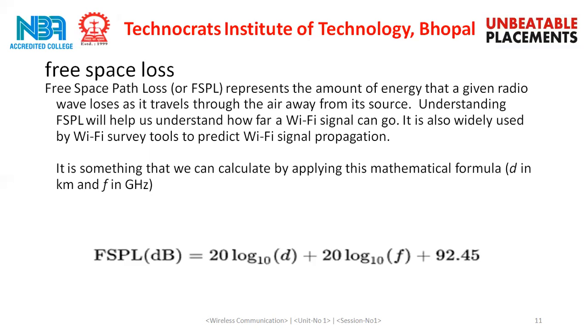So now, connecting with free space loss again, we can calculate it by applying this mathematical formula. We will take this mathematical expression, which is equal to 20 log to the base 10 of d plus 20 log to the base 10 of f plus 92.45.